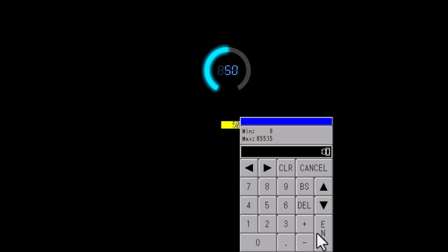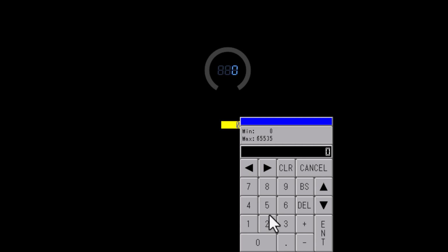However, there is one thing you need to be careful of when using a circular drawing type, a Smart Design Gauge. That is to only support input values between 0 and 100. So if you enter a value over 100 like this, the gauge will disappear. If you want to display a range of the gauge other than 0 to 100, scripted scaling is required basically.